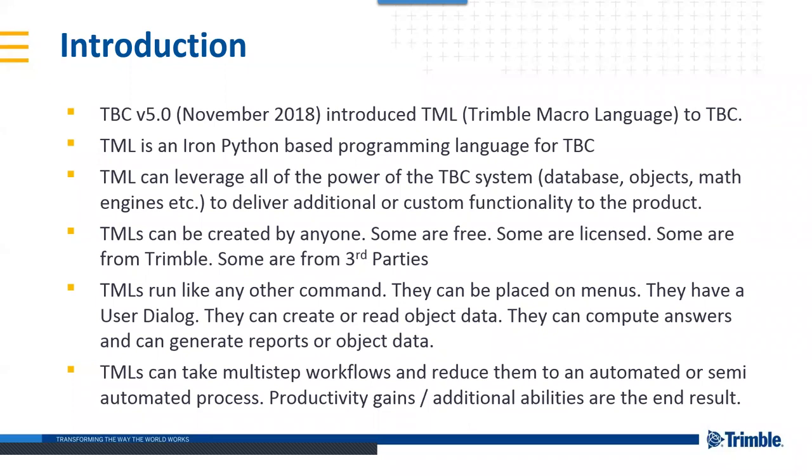So TMLs, when you run them, they run like any other command. They can be placed on menus. They have an icon that you use to get access to them. They appear in the command list. They have a user dialog when you run them. You can use them to select objects and then run processes and compute results and generate outputs, whether it be reports or object data. And TMLs can take significantly complex multi-step workflows and reduce them to an automated or semi-automated process, which at the end of the day gives you productivity gains and additional abilities within the software to do things that you just can't do today or you just can't do easily today.